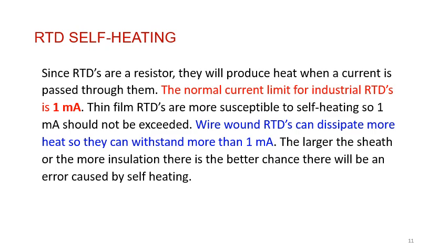The self-heating of RTD: one of the problems in RTD is that when we want to convert the resistance to voltage, we are going to let current flow in the RTD. To make this clear with a very simple circuit, if this is the resistance and here is the RTD, then the voltage here on the output, if you remember when we convert the resistance to voltage, this kind of circuit is converting the resistance to voltage.